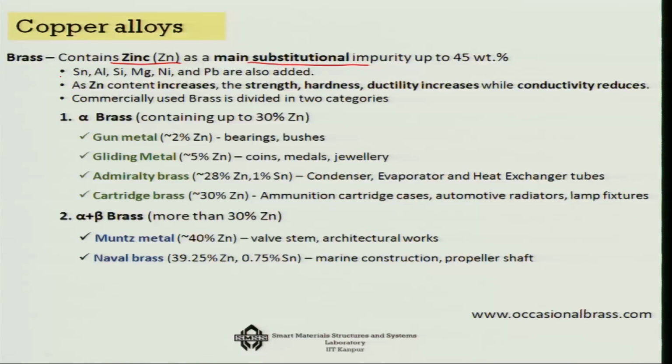Also tin, aluminum, silicon, magnesium, nickel and lead are also added. And an important thing about zinc addition is that if zinc increases, its strength increases, its hardness increases, ductility also increases, but the conductivity reduces, it comes down.